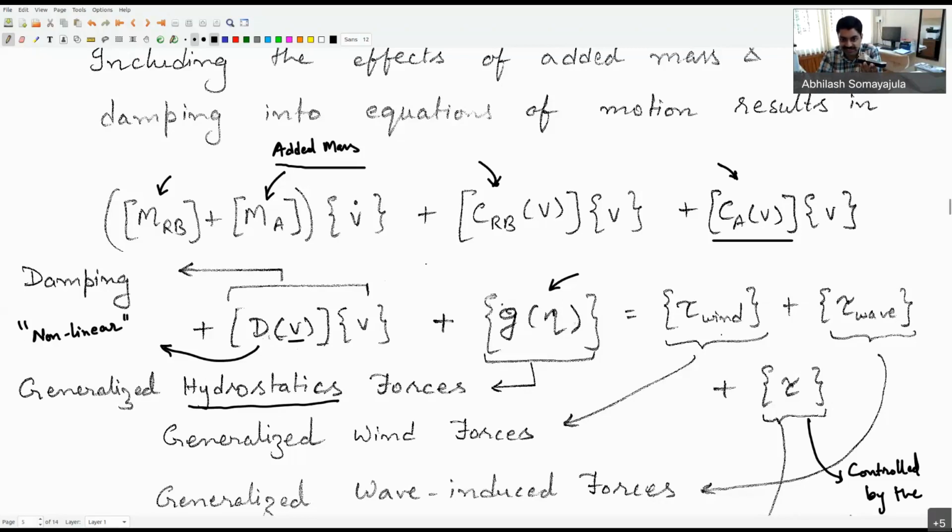That is our interest in dynamic positioning, isn't it? Yes sir. So in that case, we are not really bothered about whether it is rolling by 2 degrees or whether it is pitching by 1 or 2 degrees. That's really not a big concern. But if the vessel moves away by 5 meters, then the crane operator really has to figure out where is my crane point and why the ship is not in the position where I wanted it to be.